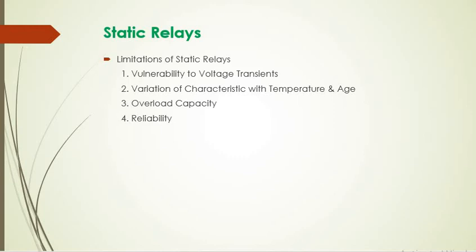Due to the advent of integrated circuits which replaced discrete components, the reliability of static relays has considerably improved. Improved testing facilities and accelerated live tests also have increased the reliability of static relays, and hence they are replacing electromechanical relays in the field at a very fast pace. So these are the advantages and limitations of the static relays.